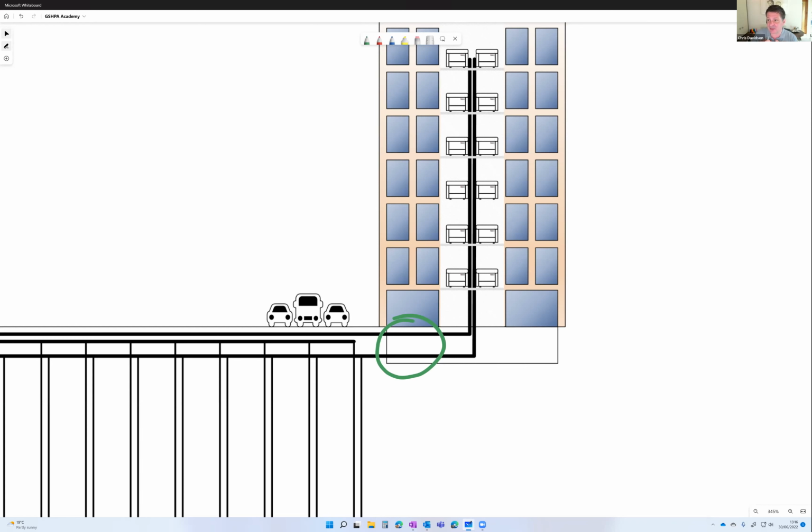I certainly design those out, and what we actually do is spend an awful lot of time on the hydraulics of these systems to make sure that the tiny little circulation pump that's inside this heat pump can deliver enough water to that heat pump if there's one heat pump running, or as I've drawn it here, if all 12 heat pumps are running. And that could be 200 heat pumps as well. So the hydraulics of these systems are very, very complex and take quite a lot of designing. So just bear that in mind.